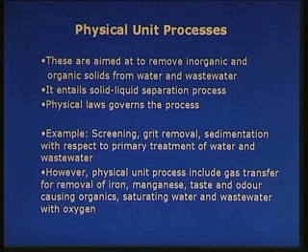Primary treatment is a physical chemical process. So, I would like to go into the primary treatment of physical chemical unit. Here, this is a physical unit process, and these are aimed at removing inorganic solids mostly and organic solids to some extent from wastewater. In fact, it entails what is called a solid liquid separation process,